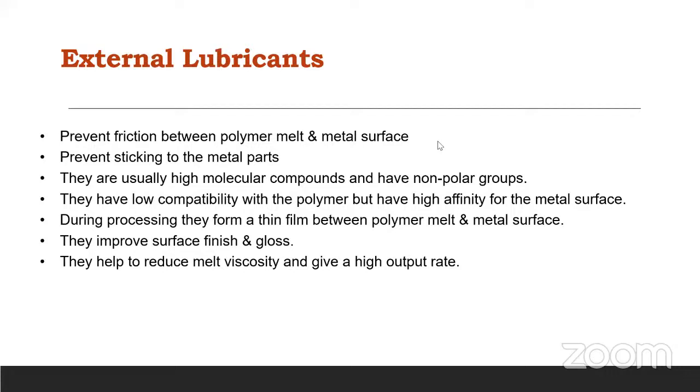There is a certain mixer. In that mixer, your PVC powder is fed, and the plasticizer is also fed, and it is mixed for a few minutes, so that there is a certain time allowed for your plasticizer to wet the PVC powder surface. Due to this action, we can ensure that your additive is properly mixed and well dispersed into your polymer matrix. Got it?